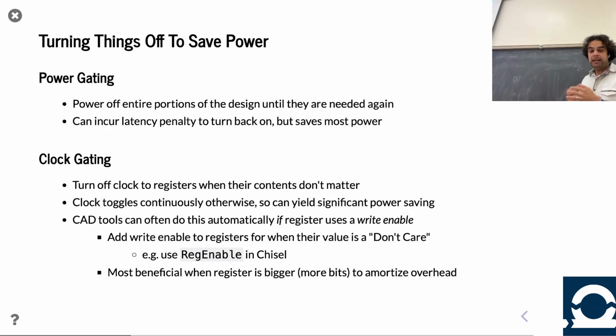Additionally, there is something called clock gating, which is much more fine-grained. On the components of your system, you expend power toggling them when you change the values on wires, logic gates, and registers. However, if those signals don't change, they won't expend additional dynamic power. They may have leakage power, static power, but the dynamic power won't be that bad. However, there's one signal in your design that's always flipping. It flips twice per cycle. It's the clock, right?